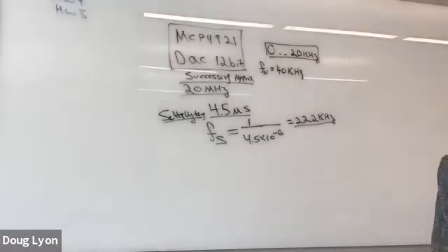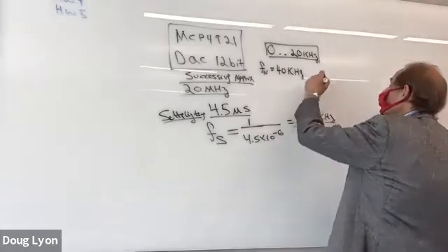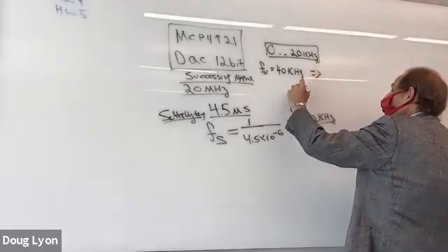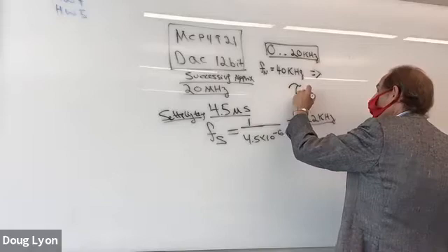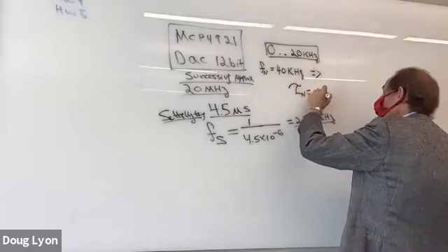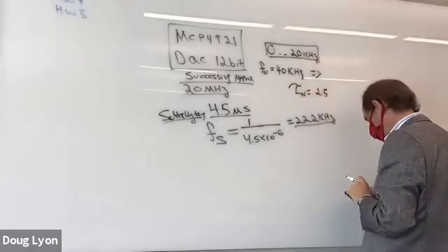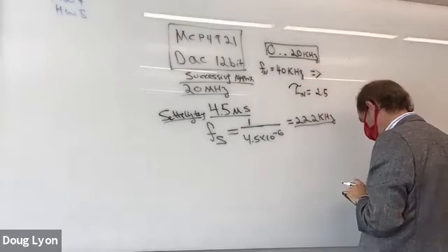So how fast is that? Let's take a look. 40, let's see. We'll do it this way. 1 divided by 40000 equals, a period for Nyquist is going to be 2.5 times 10⁻⁵.